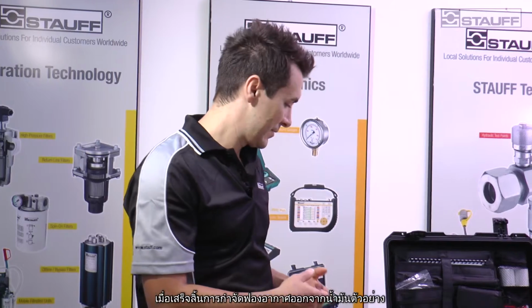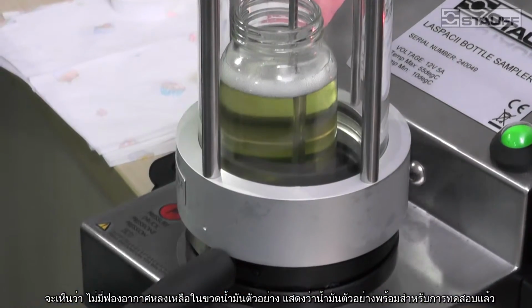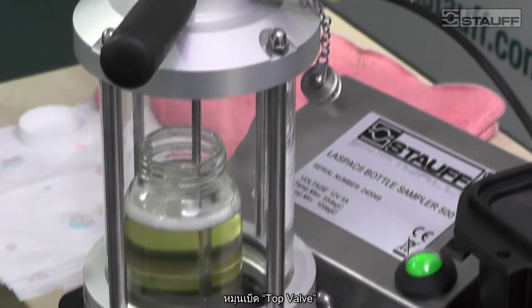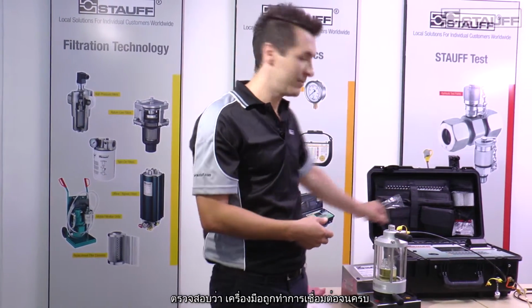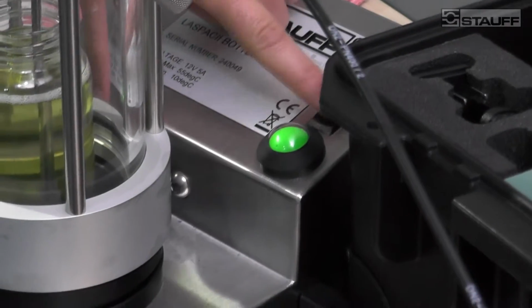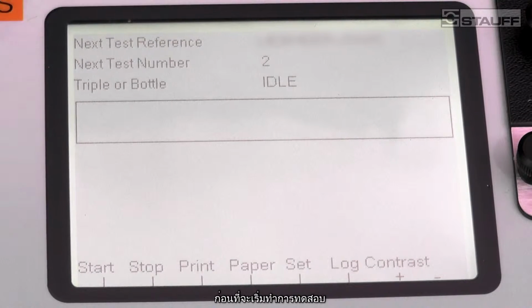Once we finish removing all the air bubbles, so there's no more bubbles down the bottom, so now we are ready to turn it off and then commence the test. So we turn the bottle sampler off, open up the top valve, change the handle to pressure mode. When the machine's already set, so make sure the machine's turned on, and then start the bottle sampler in the pressure mode. That's it.